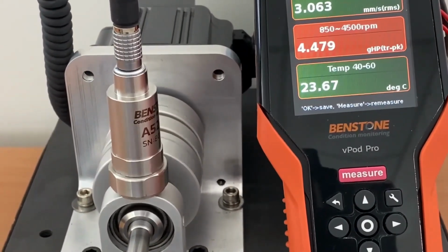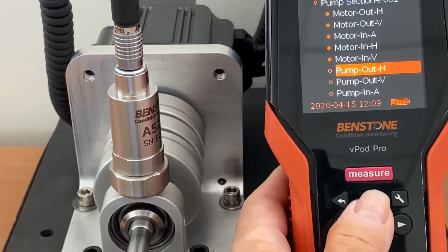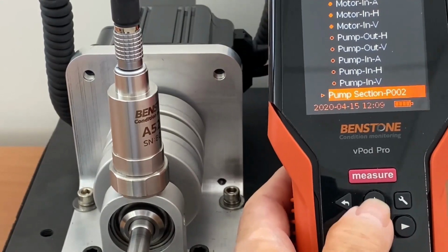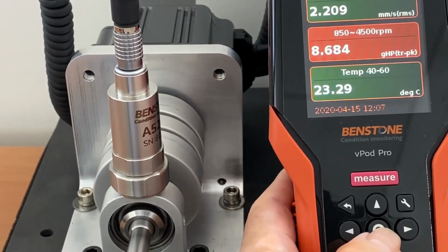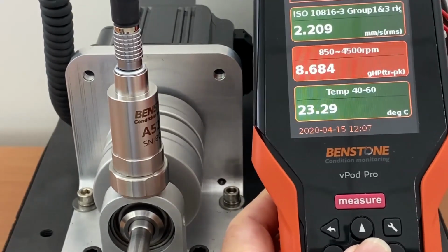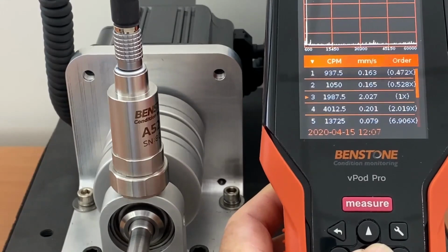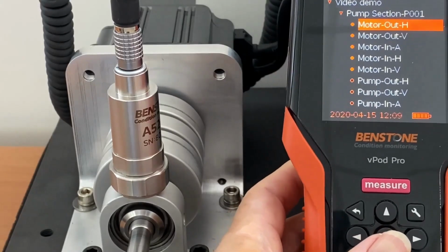If you notice, in this demonstration, we have installed a bad bearing to show how the measurements can be seen more clearly. As you can see, the bearing's true peak value is very high and is over the alarm levels. Now if we go back to the point to look at the archive data, you can select the point that you wish to look at by pressing the OK on the vPod Pro, and it will display the measured and saved values. Press OK again, and now we can view the spectrum of the data points selected. And once again press OK, which will bring us back to the route mode.